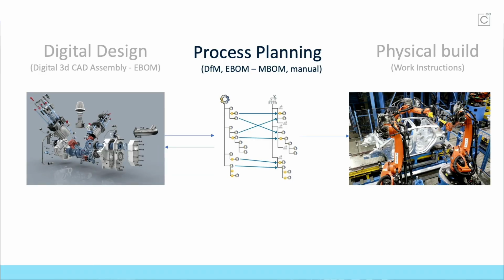And fundamentally, it's a problem about how to convert one structure, one representation of a product into another representation. So the EBOM is the engineer's view of the product. It's a functional breakdown of the product into sub-assemblies that typically have their own distinct functions, like a hydraulic system or pneumatic system or structural system. But that needs to be converted into the manufacturing bill of materials, called the MBOM. And today that process is entirely manual, right? You use PLM systems and you use very archaic techniques like creating exploded views and PowerPoints and screenshots, and it's really painful and it's messy.